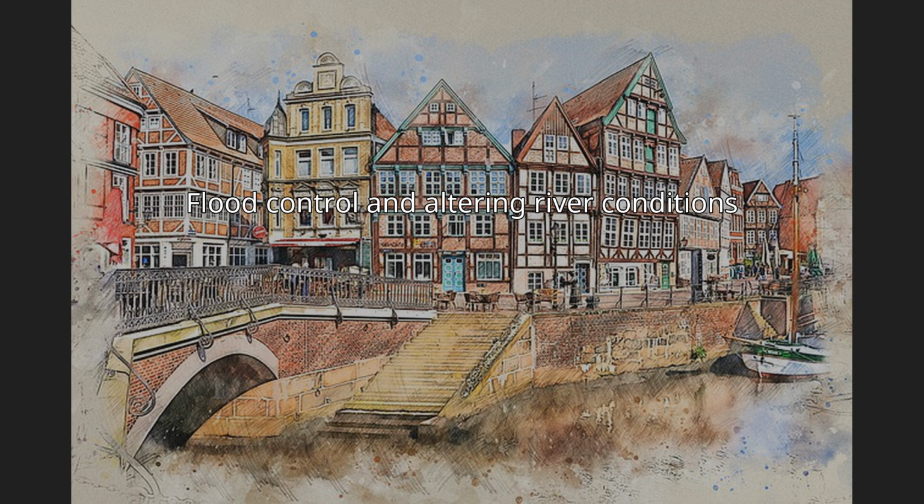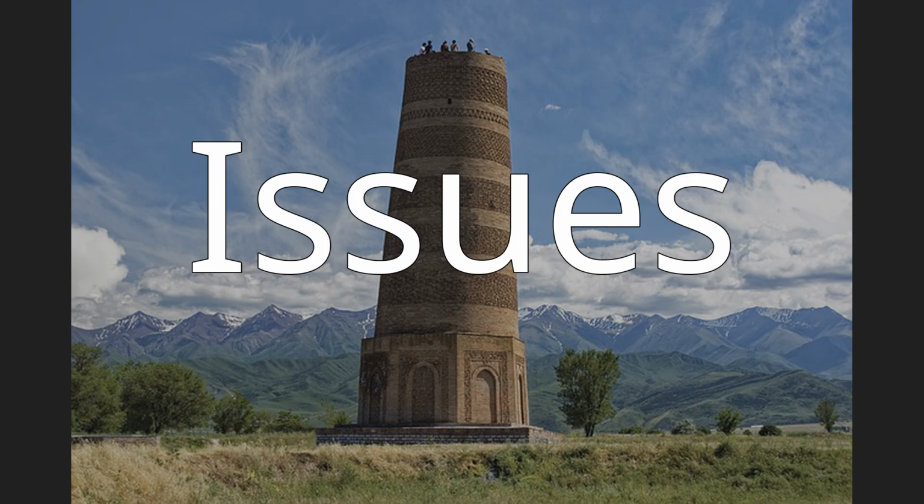On larger rivers, a weir can also alter the flow characteristics of the waterway to the point that vessels are able to navigate areas previously inaccessible due to extreme currents or eddies. Many larger weirs will have construction features that allow boats and river users to shoot the weir and navigate by passing up or downstream without having to exit the river. Weirs constructed for this purpose are especially common on the River Thames, and most are situated near each of the river's 45 locks. Issues.